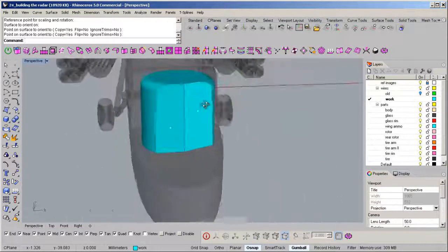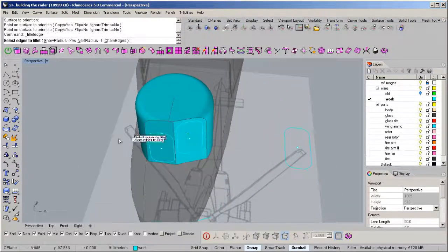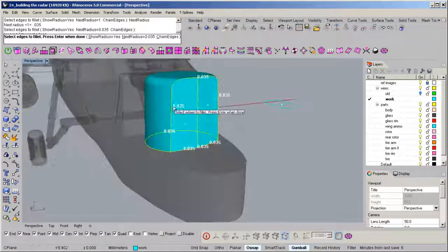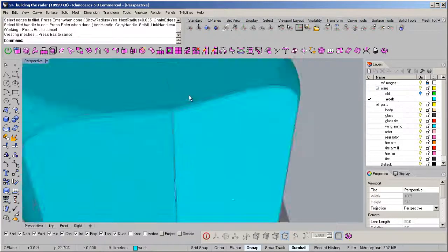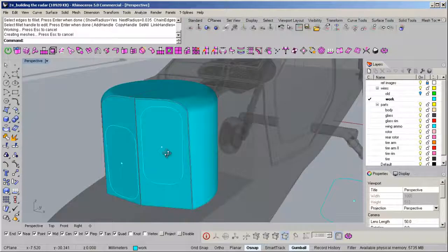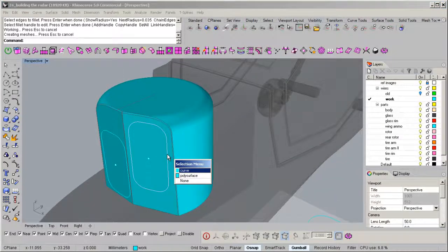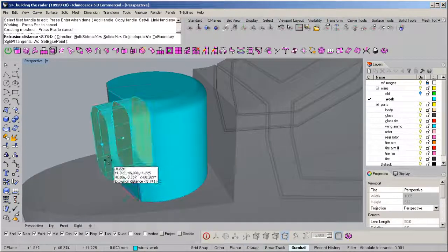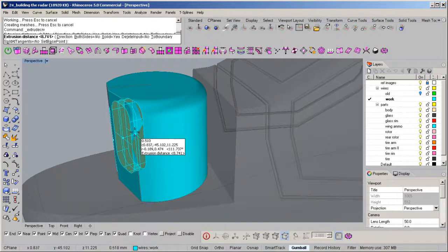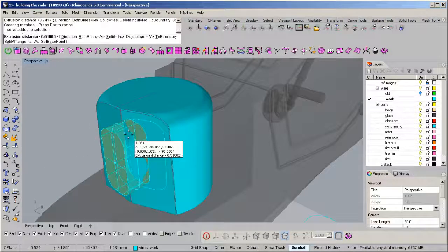Before we cut it out, let's make sure we can do a fillet around every sharp corner here. Radius, we'll do 0.035 again, and just select all the edges. It's not bad. Now we can take this curve and do an extrusion. Pull it in. Do the same.